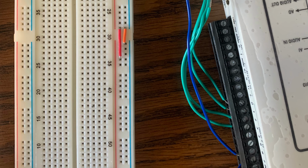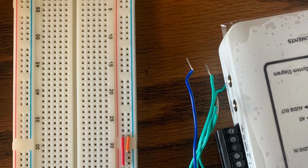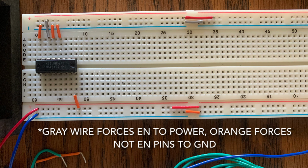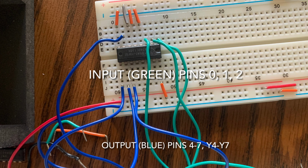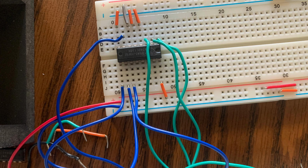First, we set up our breadboard, connecting power and ground from the MyDAC to all power and ground lines on the board. Next, we set up and test our decoder. There are 3 enable pins, 2 which we will set high and 1 which we will set low, because we always want the decoder to be enabled. Then we can test the decoder by connecting 3 input pins, 0, 1, and 2 to A0, A1, and A2, and test the outputs, watching for the active output to go low.